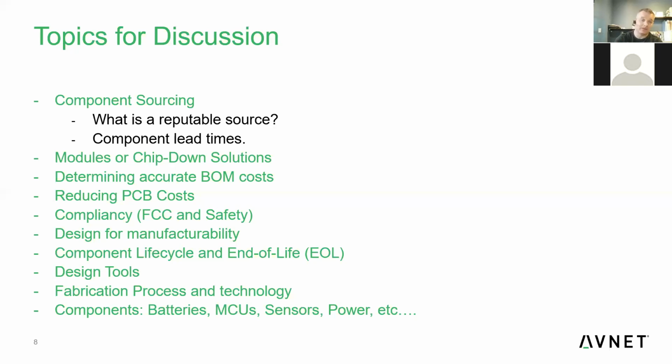So say it is a screen, a display, in your product. Obviously, switching out is not easy, but giving you a 6 months warning allows you to at least forecast what you think you will consume and build a buffer so that you're able to replace that part with something else. That's the intent, but it can be tough getting the notices. Like in this case, I was intimate with it and I was tracking it, and I still missed it. It never got sent to me. So sometimes they will pass you by and you won't notice them.